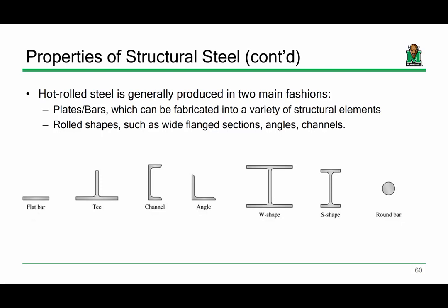No, I just want to make sure that the terminology is consistent with today's practice. If you hear the term H-piles, they're talking about foundations. And there are a particular series of shapes produced by the steel industry for piling. It's just a steel shape, a steel cross-section. It's a little thinner, and the yield stress is a little lower because you don't really need it because you're relying on friction and tip capacity and whatnot. But yeah, it's just a different shape. Any questions?